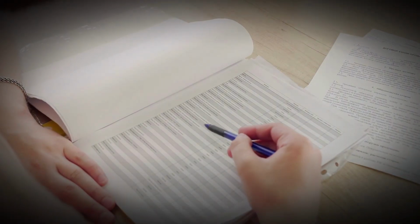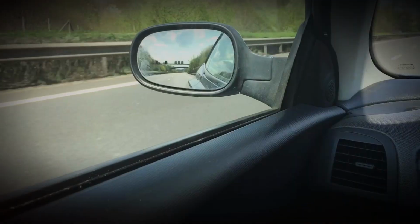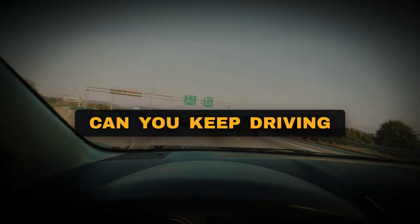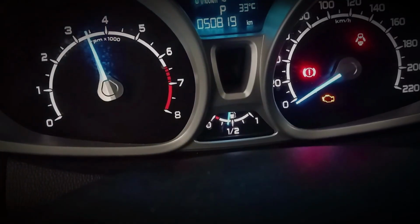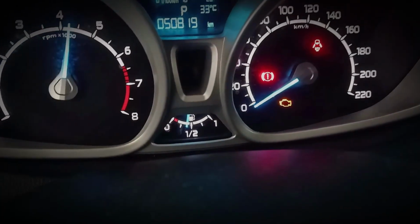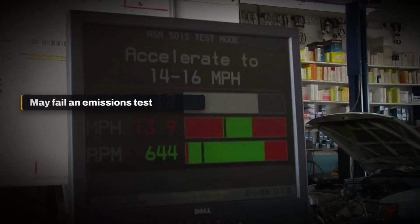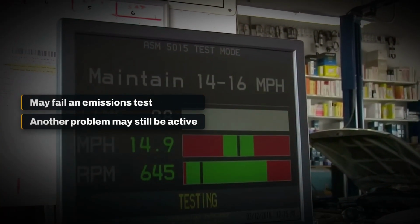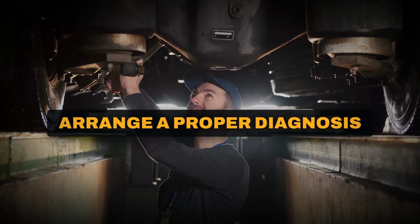Also, ask whether the converter is still covered by an emissions warranty or manufacturer campaign. That check should happen before you pay for the repair. Can you keep driving? A steady check engine light with P0420 does not always mean the vehicle will stop running immediately, but the code should not be ignored. The vehicle may fail an emissions inspection. The converter failure may also be the result of another engine problem that is still active. Limit unnecessary driving and arrange a proper diagnosis.